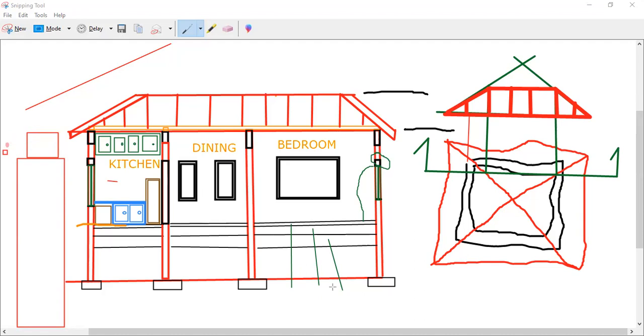You want to ensure that the notch is created. So you bring this line in until the notch is created here. Then you trim out this section. No, you offset first. Offset to get the thickness for the rafter. Then you trim out the notch.